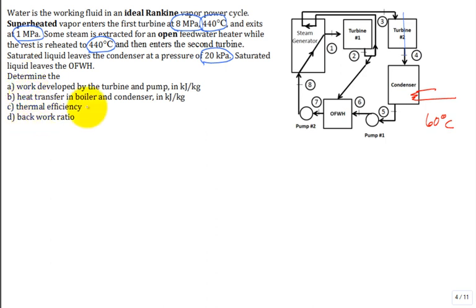And then we go through and make a lot of calculations of all of these metrics, especially the overall thermal efficiency and the back work ratio. Have we outlined the work of the first turbine stage? Have we done that enough? Energy balance shows that it's H1 minus H2. And I put it on a per kilogram basis, so this is kilojoules per kilogram.